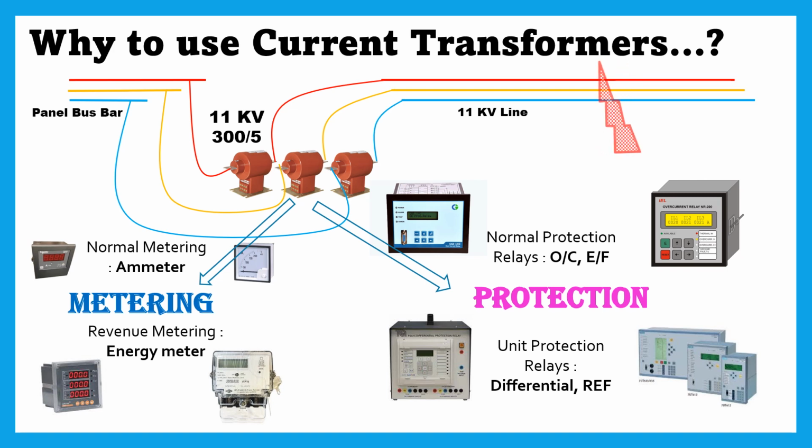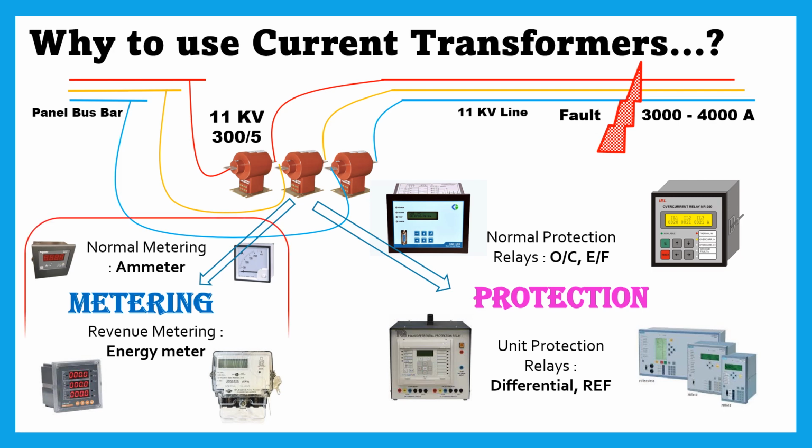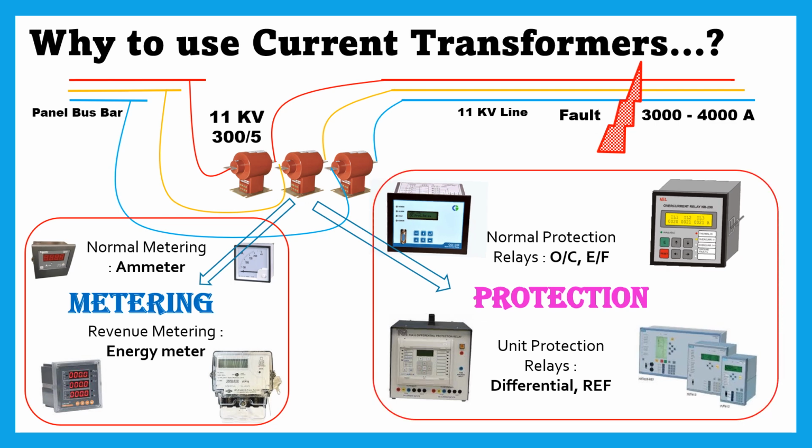You know that electrical faults are an unwanted feature of electrical circuits, and whenever one happens, primary current in the CTs reaches thousands of amperes. So connected metering equipment may get damaged. How to deal with this situation? You can understand that one option is to manufacture metering equipment capable of bearing such heavy fault currents, but it will surely increase the cost. Another option may be that this fault current should not get passed through this equipment so that smaller capacity equipment doesn't get damaged. But at the same time, you require the feeder to get tripped, or say protection CTs to work.